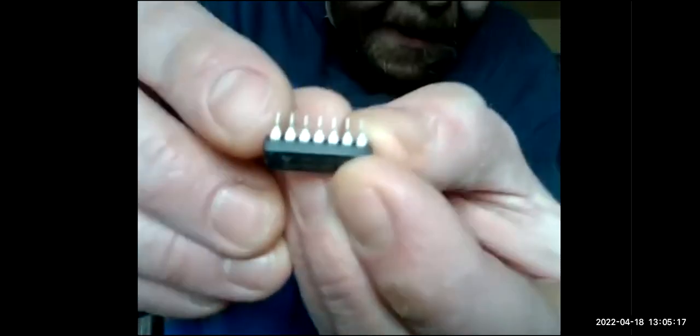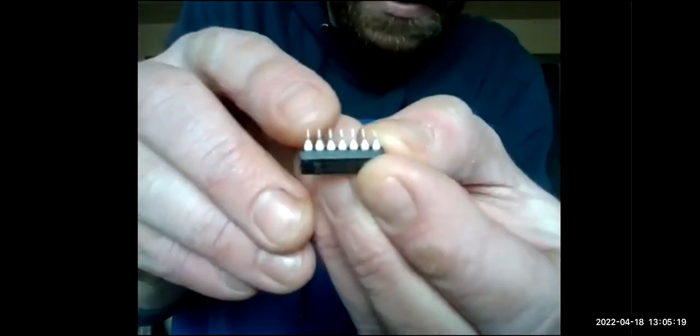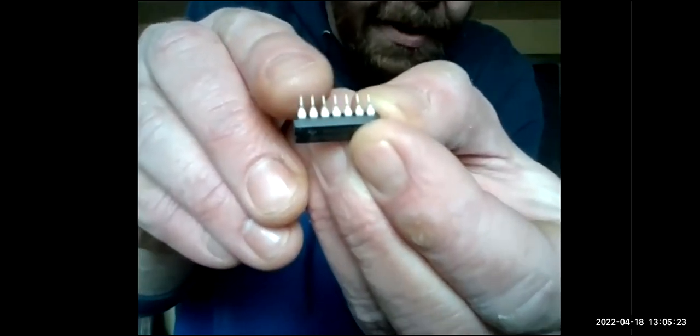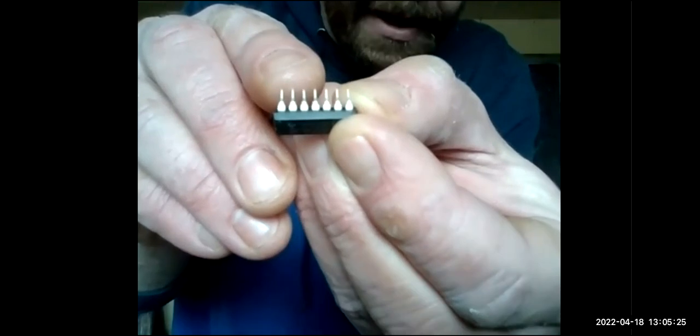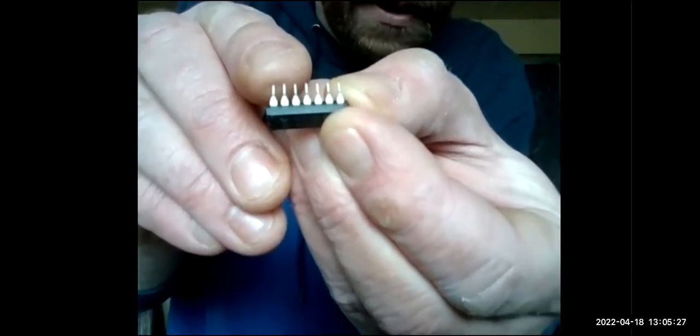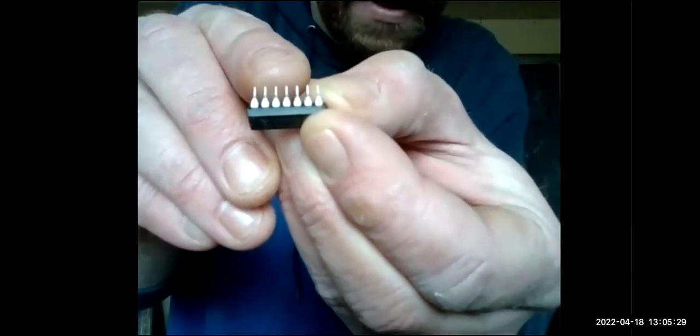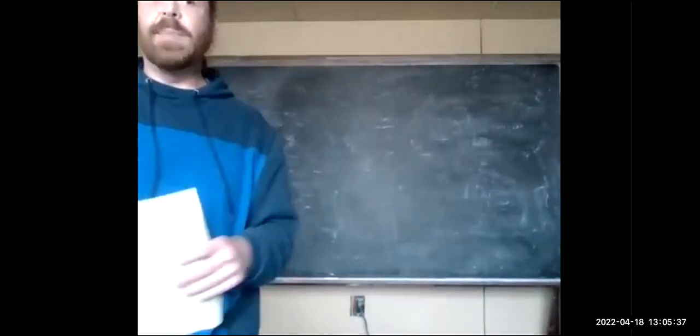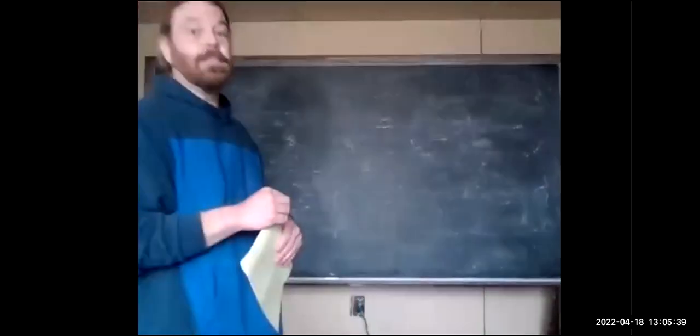This first pin is where the power goes in. But then the second 2 pins, we hook wires to those. The second and third ones get 2 inputs, and then the one next to it would be the output from those 2 pins being ANDed together, which is a binary signal, so it's either on or off. So it does build up. I can visualize that.